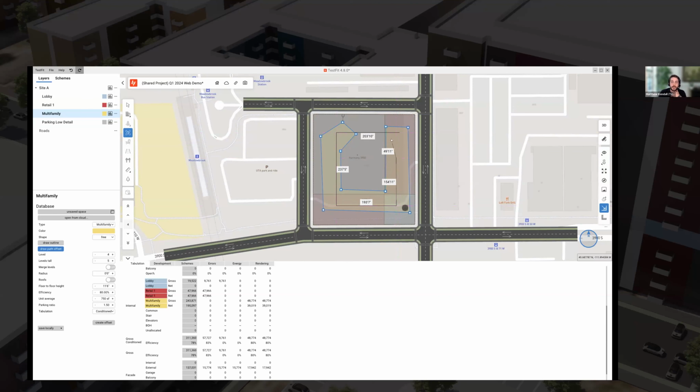What this does for us is after I've defined this initial path over here, I'll click inside of the circle and I'll set what I want my offset to be. So for this one, we'll be working with, let's say, a 30-foot deep unit, 6-foot hallway, and an additional 30-foot deep unit. So let's type that in. Oh, sorry, it should be 33 because we're working at the half point.